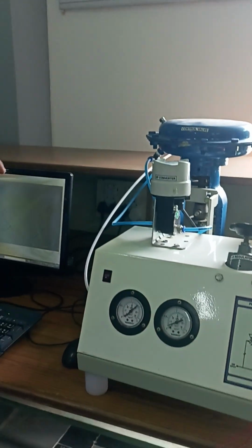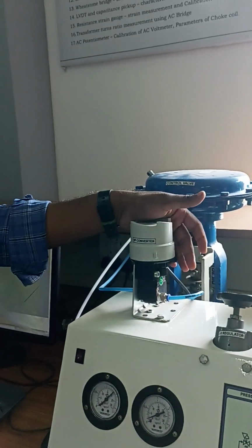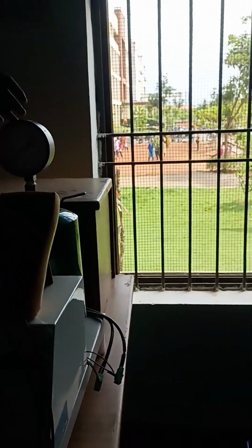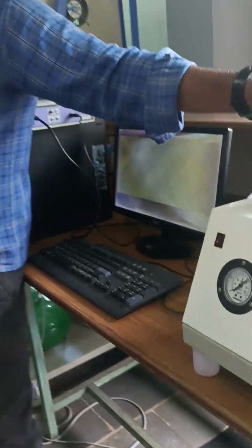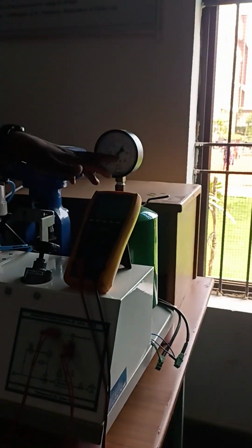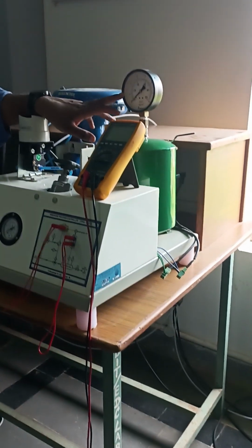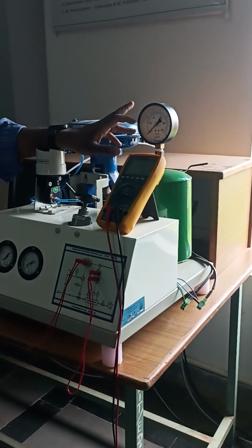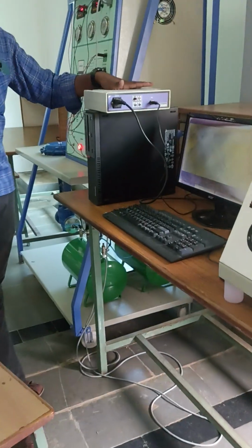So this is a DAQ, like that. Once you view the DAQ, it will go to this controller. They vary a little, and then there is an ADC. We have pressure sensors, like pressure transmitters, which give output depending on the pressure available. If this pressure transmitter works up to 5 bar, that is about 75 psi. So for 0 to 75 psi, it will give 4 to 20 milliamps, and that 4 to 20 milliamps will be given as the process variable.